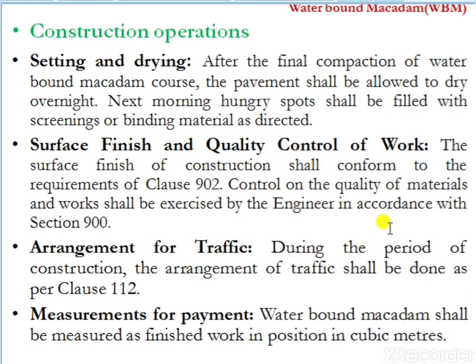So after applying a binding material, the next process is setting and drying. After the final compaction of Waterbound Macadam course, the pavement shall be allowed to dry overnight. Next morning, hungry spots shall be filled with screening or binding material as directed. So after the application of binding material, the pavement is allowed to set and dry.